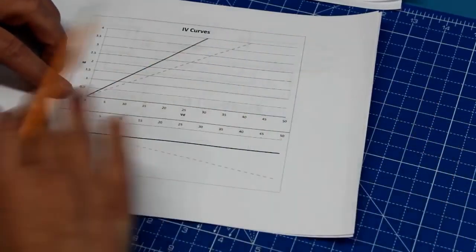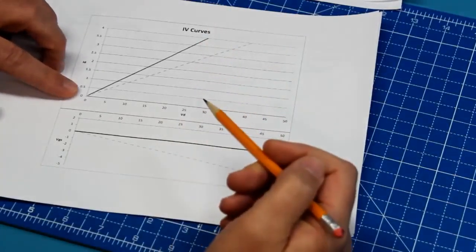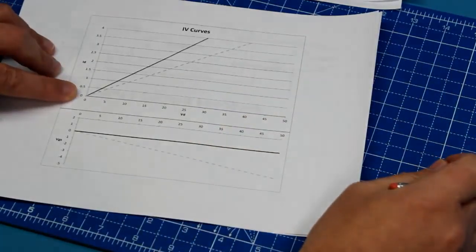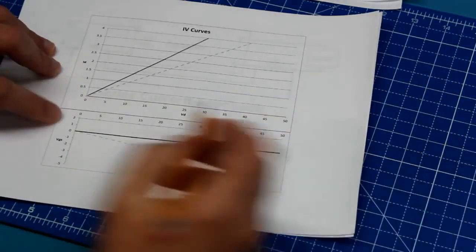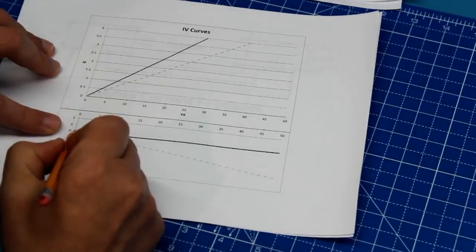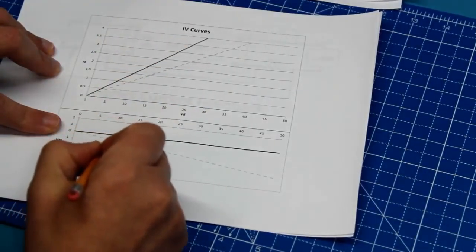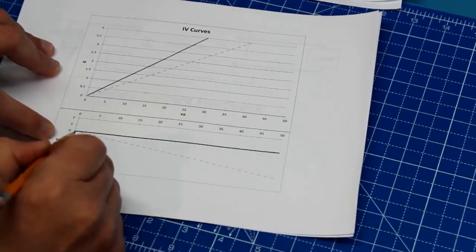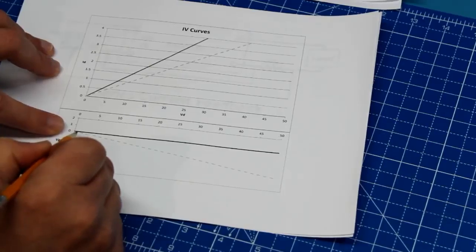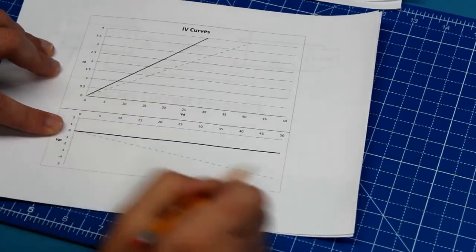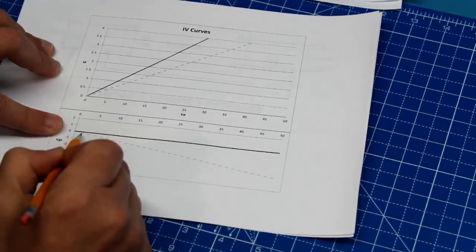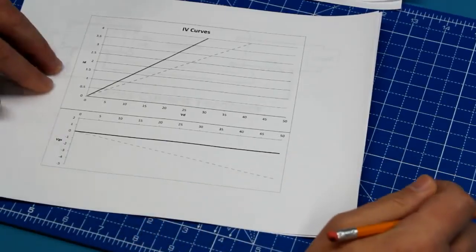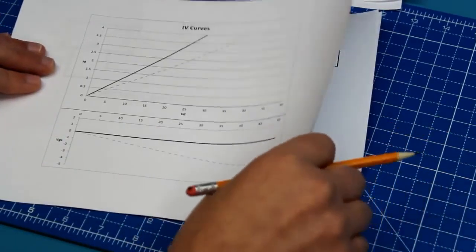So, here's another view of that. This is just one sweep, and you can see that the solid line is the original. The dotted line is with the 1 ohm source resistor, and in the original, the actual gate to source voltage, of course, is the same throughout the sweep. And in the demonstration with the 1 ohm source resistor, that's the dashed line. You can see that the gate to source voltage is changing with the sweep. And so it changes the shape of those curves.